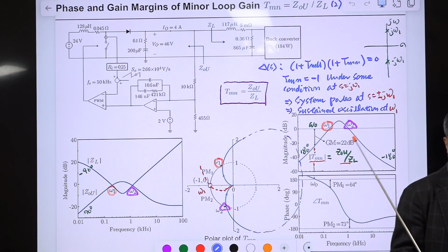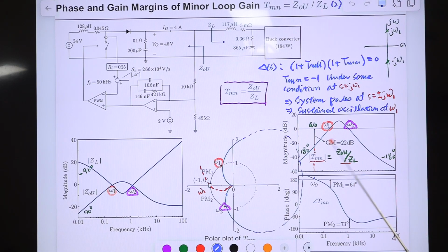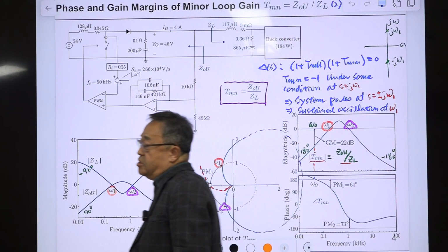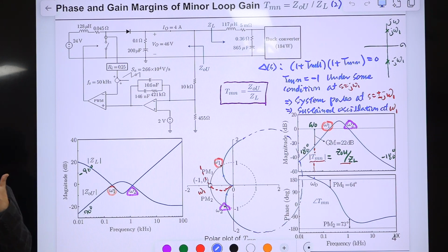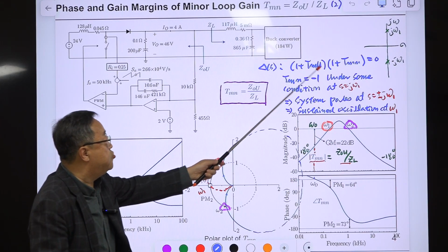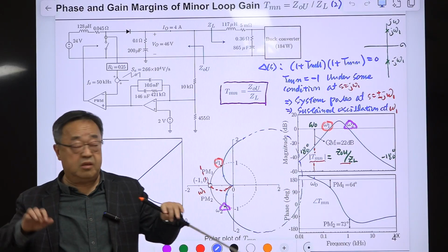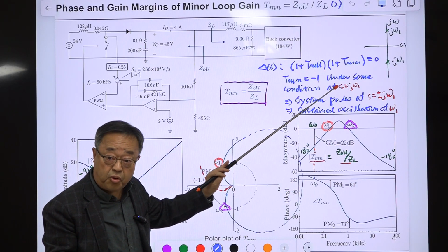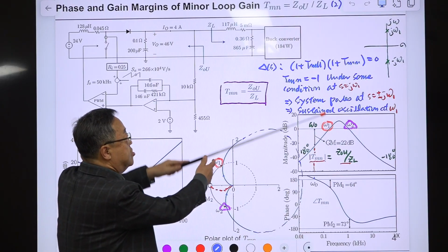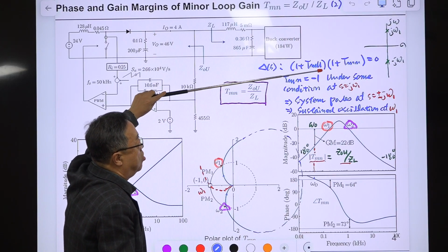So this is it. It's all about the previous discussion. This is the stability determination principle of this load coupled converter. We are assuming this part is okay because this uncoupled converter is designed by us, so it should be stable with a good phase margin. You are only worrying about this newly added part. Somehow it is entirely decoupled. The coupled result is a product of them, but the roots of this equation are the union of the roots of each equation.